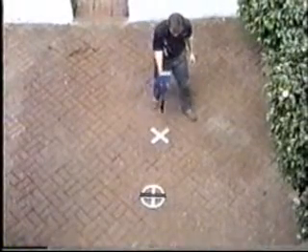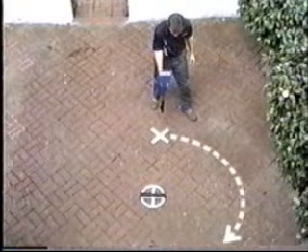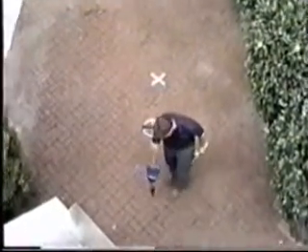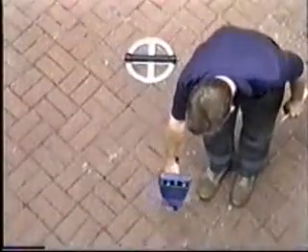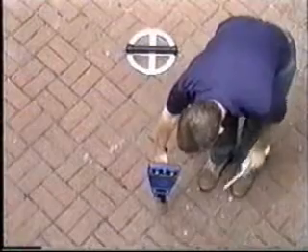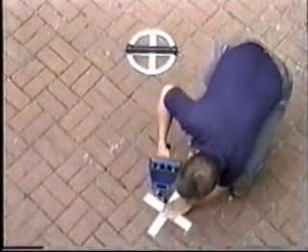To find the other side null, walk a roughly circular path away from the first mark. Continue on the circle until a second dead spot occurs. This is the location of the second side null. Mark this location like you did the first.